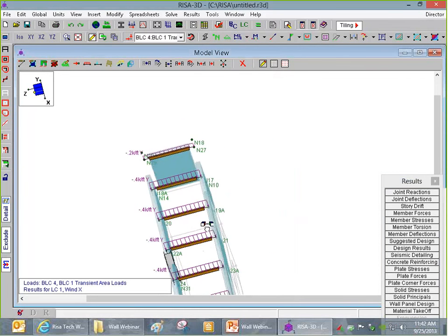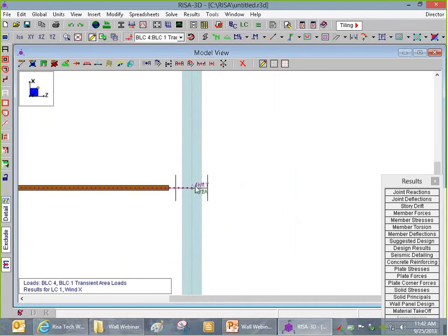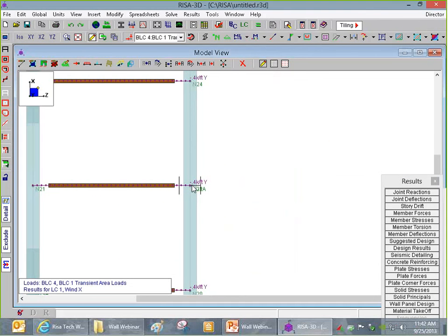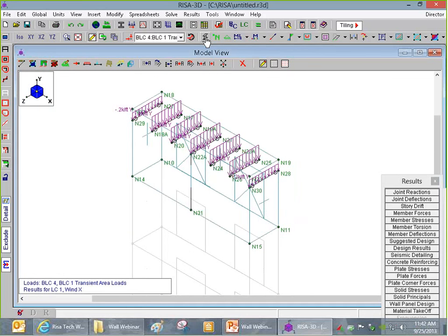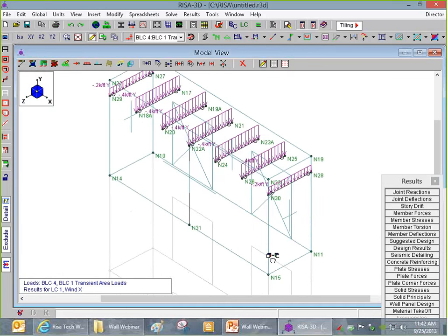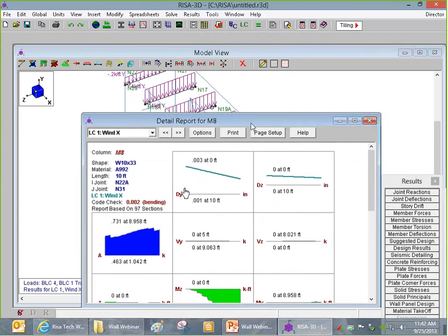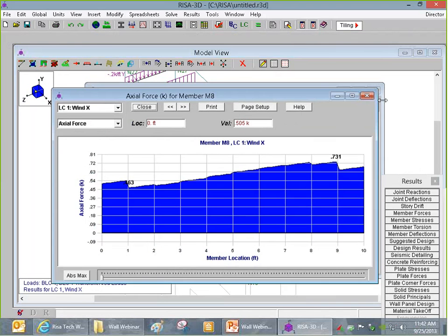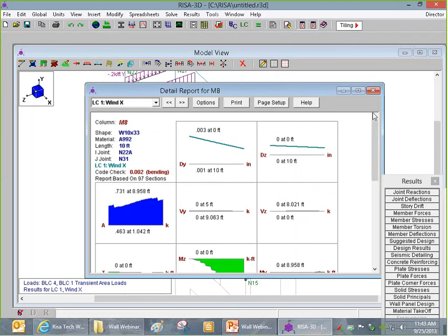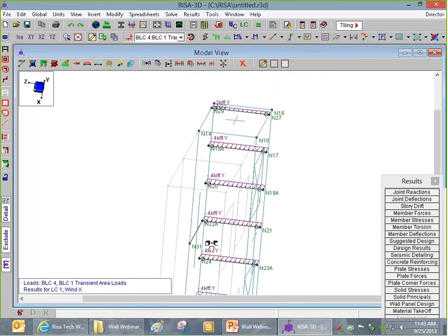So what you can see here, when I render it, maybe I can just snap into an elevation view here, is I've got this steel column now embedded in this concrete wall. Now what's going to happen is when I embed this column in the wall and I solve, this is going to fully mesh itself into that wall. And so as a result, I'm going to expect to see on this column that I've got a somewhat jaggedy axial force diagram. And what we're also going to see in this case is that the force in the wall doesn't exactly match what was at the beam.